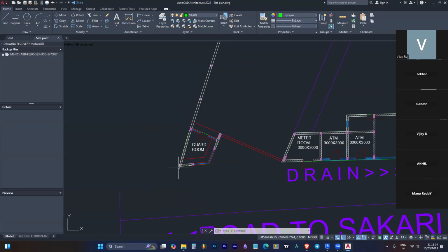If you go around here, you can see this value. This is the north and the east value, the x and y value. If you hover over it like this, you can get one data from here. This will be the survey point of north and east value. So you have to type down all these numbers like